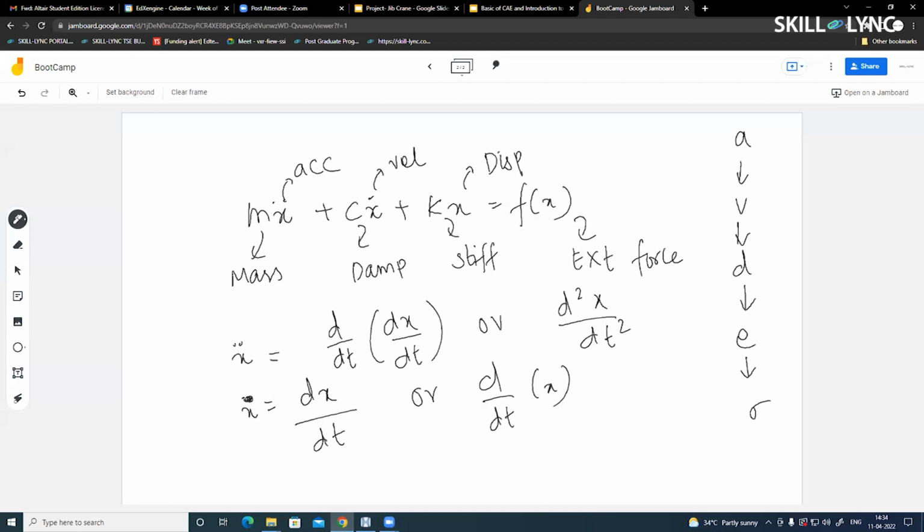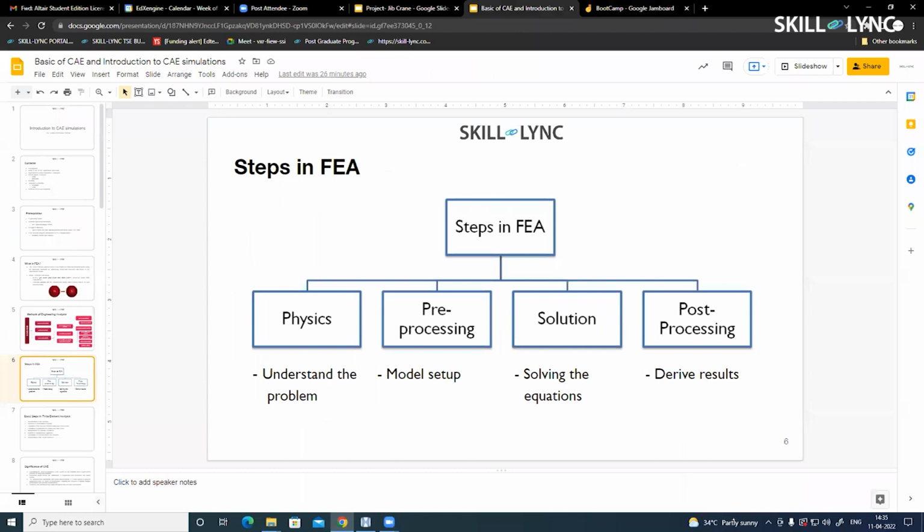From displacement, I don't integrate; if I have my displacement and I compare it with the original length, I get my strain. Then, using Hooke's law, which states that stress is directly proportional to strain, if I remove the proportionality and put in a constant, which is Young's modulus, I can easily get my stress, right? This is how I compute all the solutions.